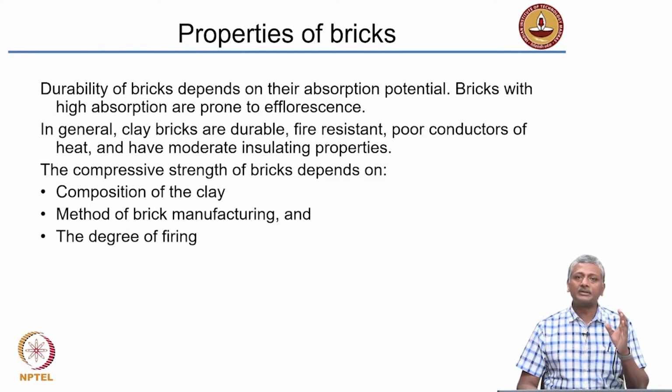Now, as I said, typical building bricks are designed for their strength and for their resistance to water absorption. A lot of the issues of durability of the bricks deal with the absorption of moisture by the brick. And that is a very important aspect to remember. If you can protect your brick from moisture absorption, you have greater durability that you can get from bricks.